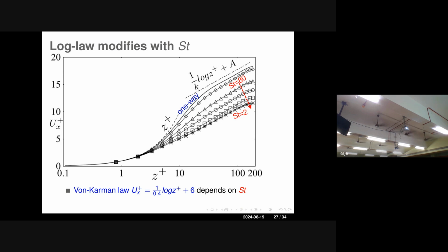So basically, it is two parts. One channel with particles going and so on, another one without particles at all. First we will simulate without particles the complete turbulent structures, whatever comes out with periodic boundary conditions. For that unladen case, whatever output comes out will be fed as inlet to this system. Definitely, the momentum with which these particles are leaving is different from the particles which are coming in.